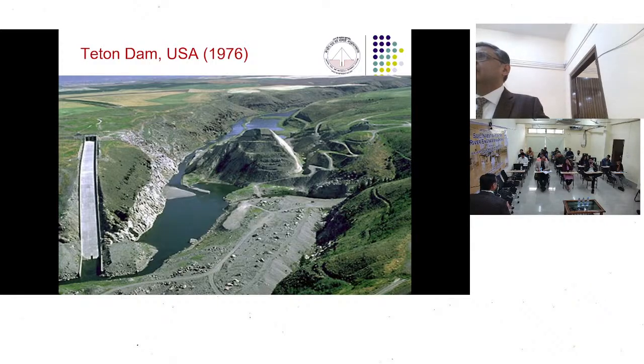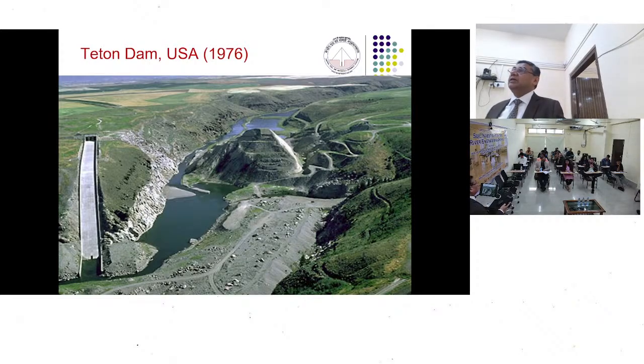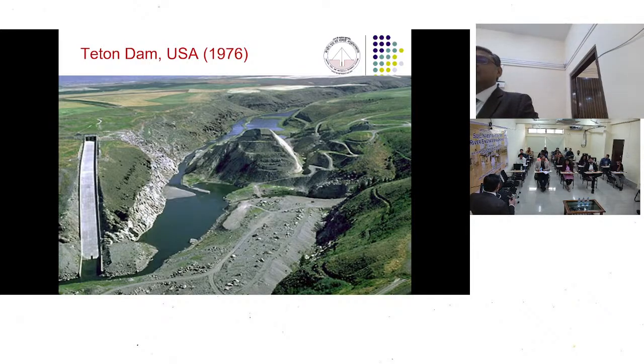Now this phenomenon was not known to the world in, I think, the early 70s or late 70s. So by the early 80s this phenomenon was known. Before that it was not known to the world, I am saying. Not just us, the world over. So some of the structures which were built before the 80s had aggregates which were reactive. And these alkali reactive aggregates used to expand, causing cracks in these structures.